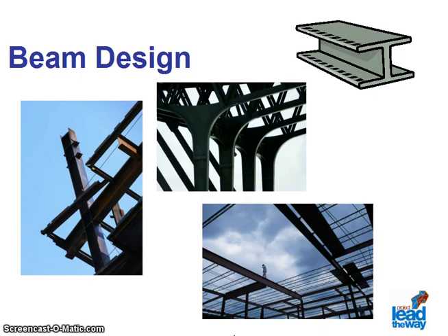Beams are used by the design engineer in roofs and floors. They may be called joists, stringers, beams, or girders. Sometimes the loads on the beams are concentrated, and other times they are uniform. All beams are designed for shear, moment or bending, and deflection. Beams are sized to safely support the loads a structure will carry with the minimum amount of material to save costs.